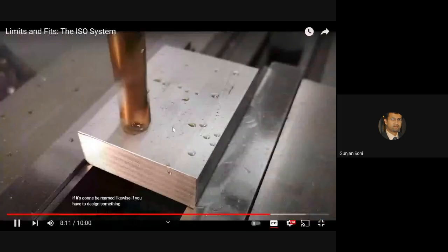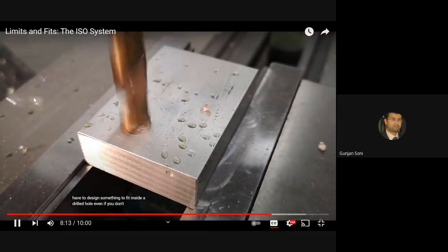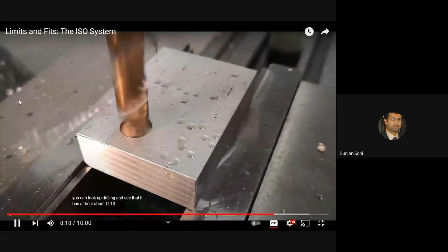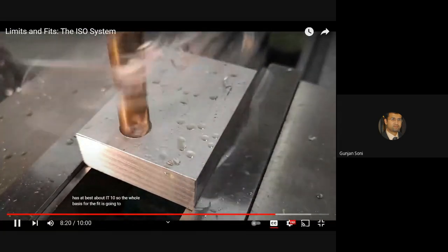Likewise, if you have to design something to fit inside a drilled hole, even if you don't have the tolerance for the hole in front of you, you can look up drilling and see that it has at best about IT10. So the hole basis for the fit is going to be around H10.